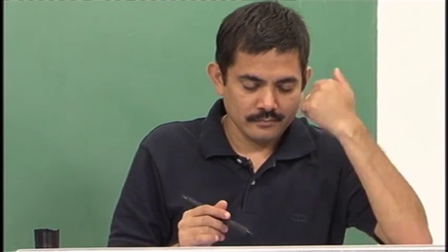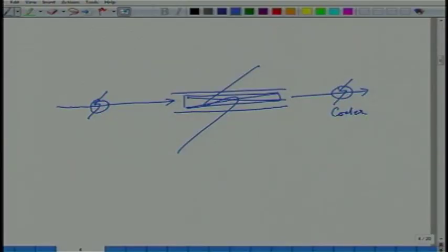Degrees of freedom, independent valves first of all. Can I put a valve here? Yes, no? I will put it, but then it is set by something upstream, or I am told that this is the amount of feed. Okay, so the valve is there, but I do not count it. Fine, fair enough. Do I need to put a valve here?